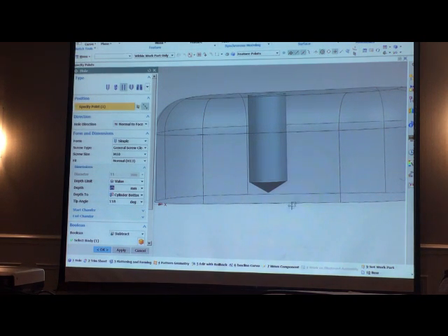Now, as a designer, I might actually be more interested in where the bottom is, but manufacturing only knows about the height of the sidewall. The reason is that's the only thing he can measure. If I tell a manufacturing engineer to drill a hole to a certain depth, he has to prove to me that he's actually drilled the hole to that depth within the tolerance that I gave him. How does he do that? By measuring the sidewall. That is what you give him. That's what the annotation call-out gives him, and that's what he manufactures.